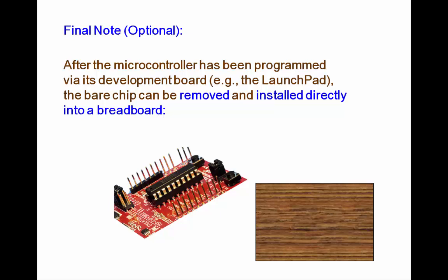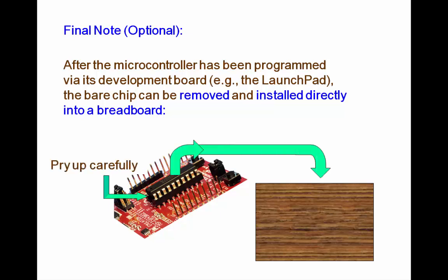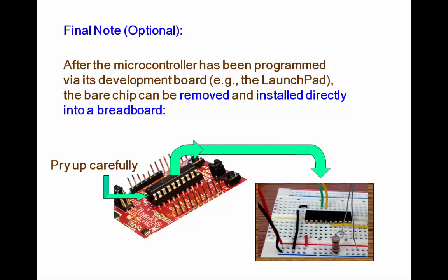After you've perfected your program and downloaded it into the chip, you can always pry the chip up carefully and install it right on the breadboard and use it without the development board to run circuits or whatever else you're having it do.